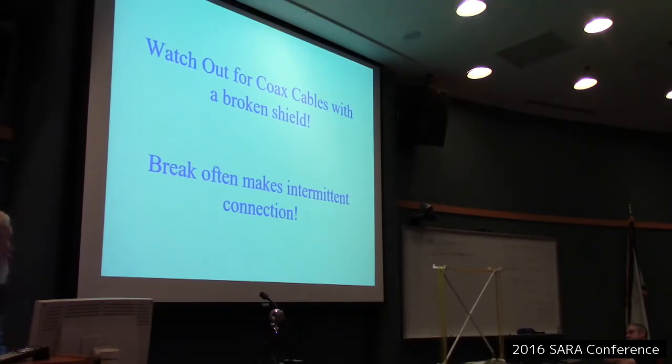Well, after I finally bumped the cable at the wrong time, I realized the shield was actually broken. That cable had been flexed so many times, the shield was broken. And sometimes it would make connection and sometimes not. When it lost connection, the receiver wouldn't quit working because it had the ground path through other stuff, but it was definitely a very bad ground path and it would go erratic. And if it quit altogether, I might have found it quicker. A broken shield like that is almost always intermittent. You breathe on it wrong, the phase of the moon changes, the cat walks by outside, whatever, and the cable makes and breaks connection. So it could be a real aggravation.